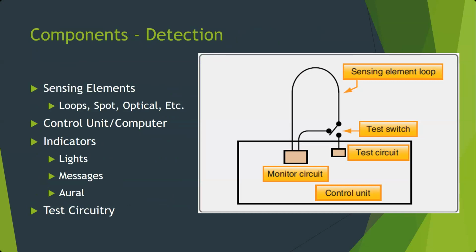Okay. The other thing it has is this test circuit. If you move the switch, for instance, in this case, that breaks the loop. So it says, okay, I can detect if there's a break in the loop, which is a caution type situation. And then the other thing the test circuit often will do is put a ground on there, which simulates something like eutectic salt melting and causing a ground. So then it can detect the actual warning function of the loops.